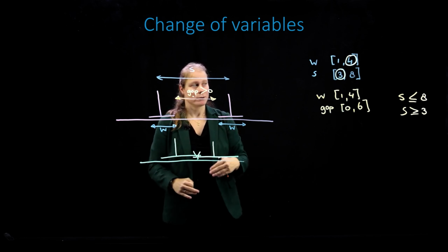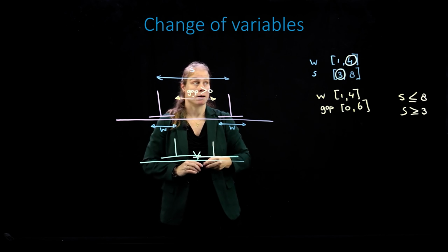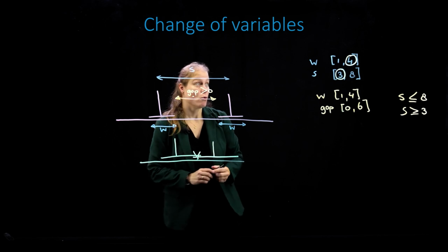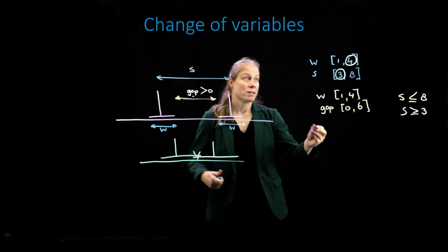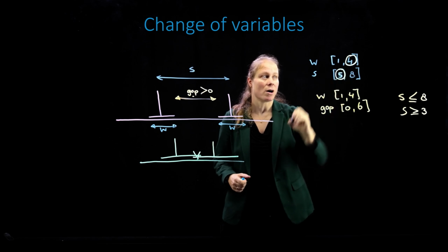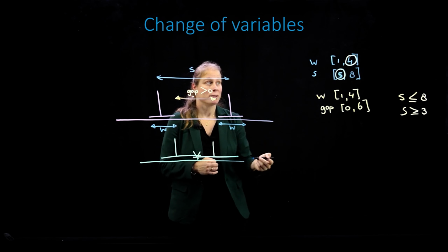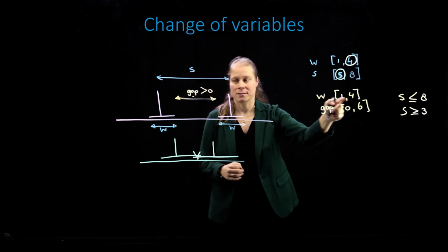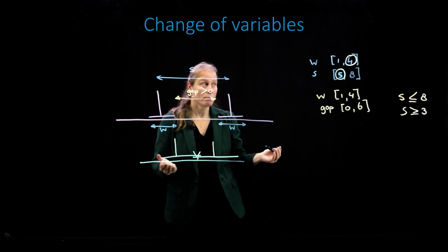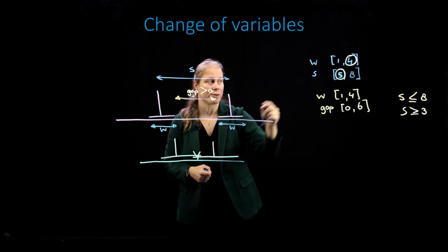So when you start defining your problem, you might want to think about which kind of combinations might actually violate this constraint. Now, if initially you said, oh, my spacing always has to be between 5 and 8, then you don't have to bother. But if in the future there might be a possibility that this number gets smaller than 2 times this width times a half, then you might want to define it as a gap in addition to the width.